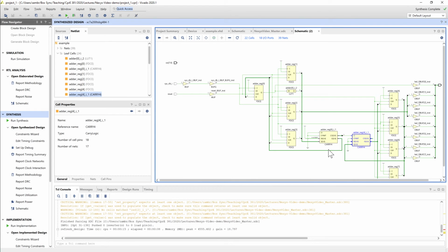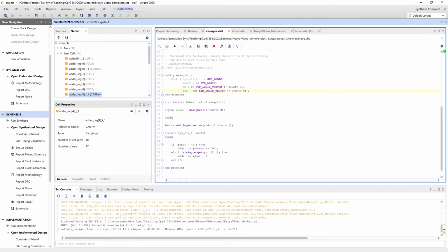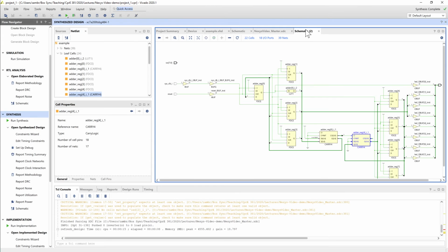You may ask, well, we did specifically specify a 32-bit adder, right? Adder is a 32-bit signal. I just happen to specify it as such. But when we look at the resulting schematic that gets generated here, it's only giving us an 8-bit adder. We've talked a little bit about this because ModelSim, even in the behavioral model generation, is doing a little bit of this.